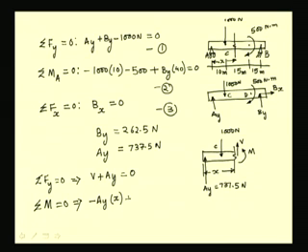So, we have plus 1000 times the moment arm, which will be x minus 10 meters, because this force of 1000 Newton is being applied at 10 meters from this end A. So, we have the moment arm as x minus 10 and we have this moment m, which is a positive moment.